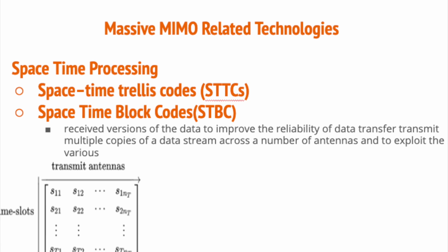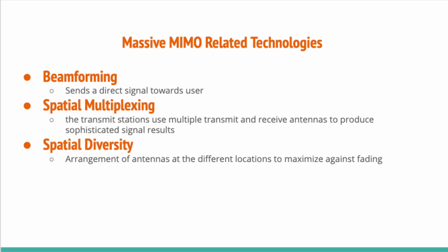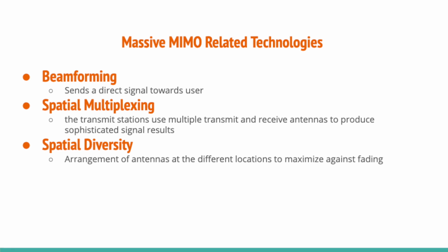Beamforming, part of the pre-coding category, has a narrow definition. In more general terms, it is considered to be all spatial processing that occurs at the transmitter. In single stream beamforming, the same signal is emitted from each of the transmit antennas with appropriate phase and gain weighting such that the signal power is maximized at the receiver input. The benefits of beamforming are to increase the received signal gain by making signals emitted from different antennas add up constructively, and to reduce the multipath fading effect.